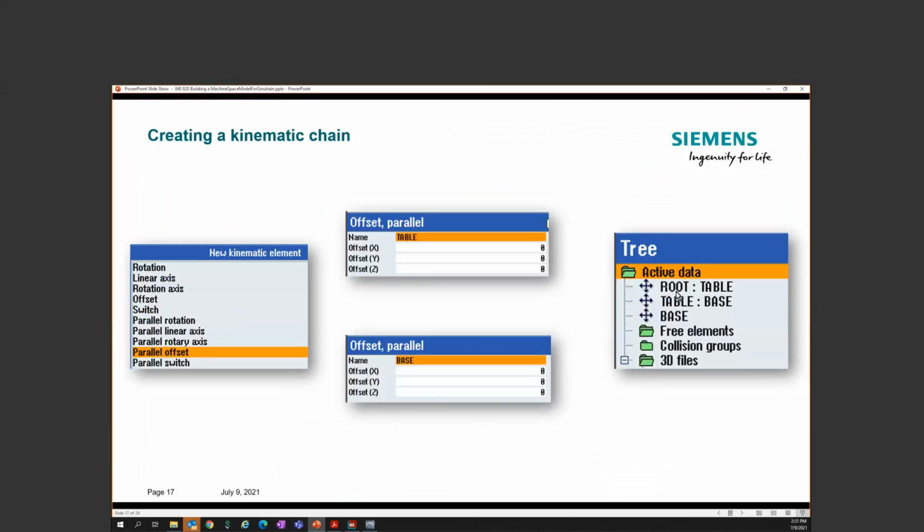I don't know if it's going to hurt you or not if you renamed it to root, but that was an MD they always had. So I always leave that first one at root. And then I like to build my separate offsets. So my root, I think of that as my head, my spindle. This is going to be my first chain piece. So any of the axes that would effectively move the spindle around would be found underneath this root chain.